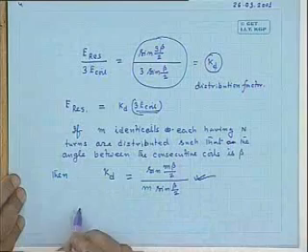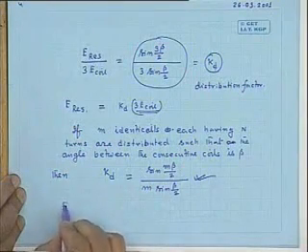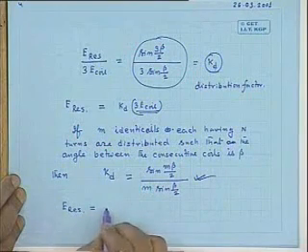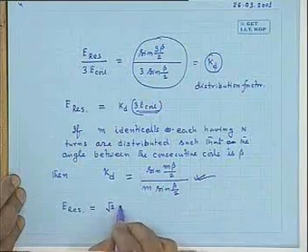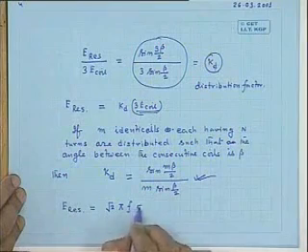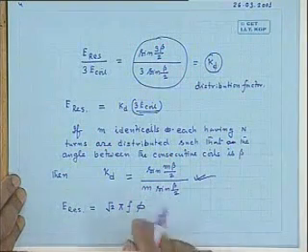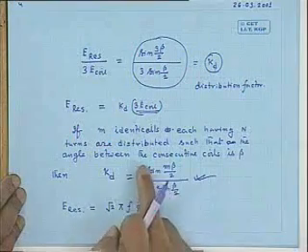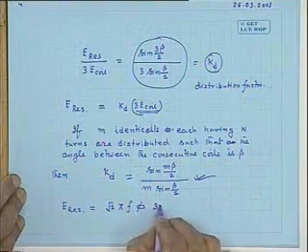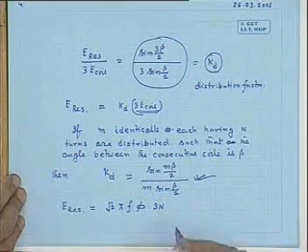Now see how easily I will write the expression for the induced voltage of the resultant. E resultant would be root 2 pi f phi, where phi is flux per pole. Now come to number of turns. There are 3 coils, each having n number of turns, so 3n should be there.